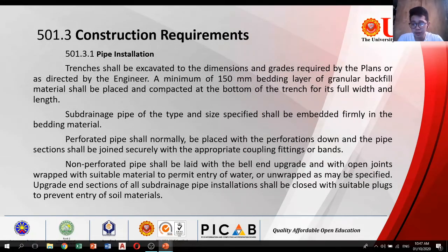Construction requirements for pipe installation. Trenches shall be excavated to the dimensions and grades required by the plans or as directed by the engineer. A minimum of 150 mm bedding layer of granular backfill material shall be placed and compacted at the bottom of the trench for its full width and length. Sub-drainage pipe of the type and size specified shall be embedded firmly in the bedding material. Perforated pipe shall normally be placed with the perforations down and the pipe sections shall be joined securely with the appropriate coupling fittings or bands.